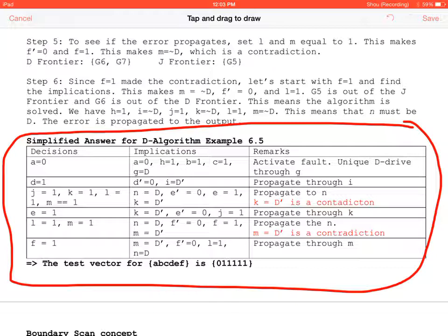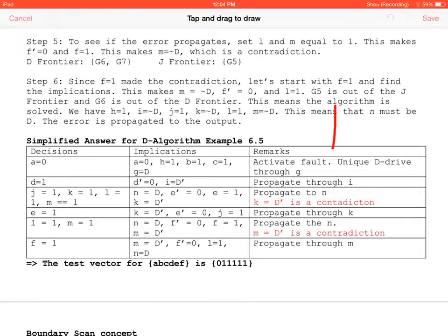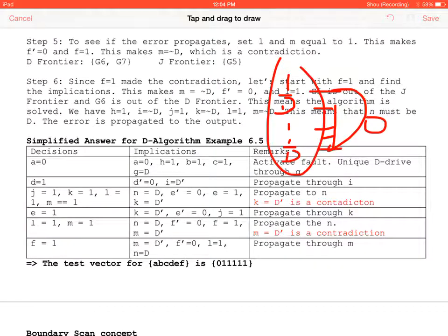So if you have, on a circuit for a NAND gate, 1, D bar, 1, D bar, well, it's still going to propagate D to your output. And you have multiple issues.